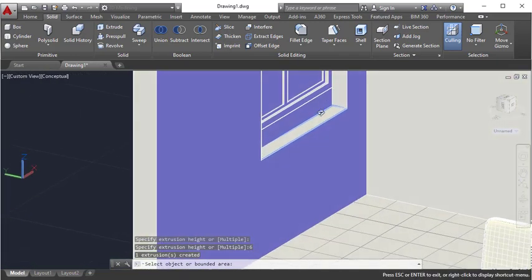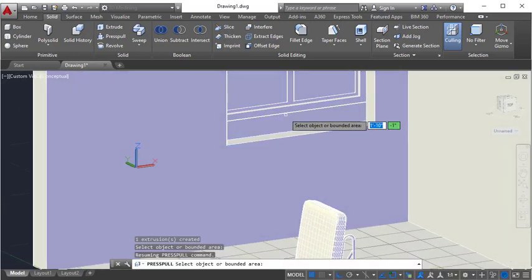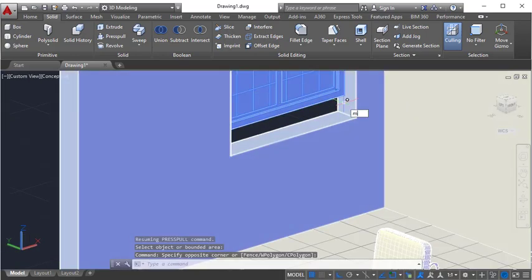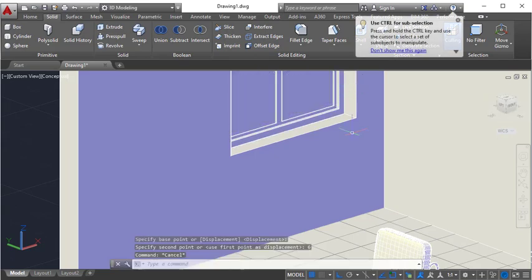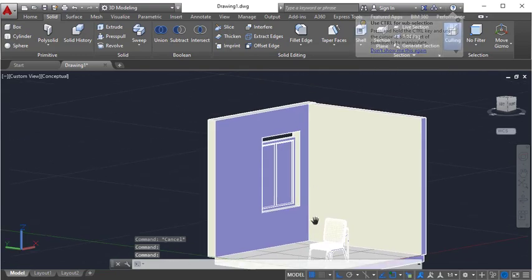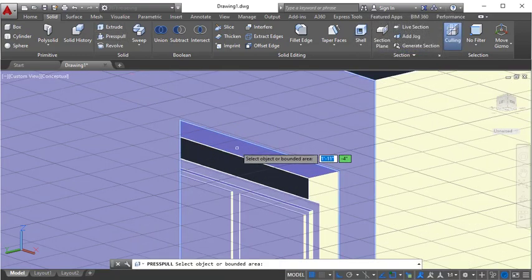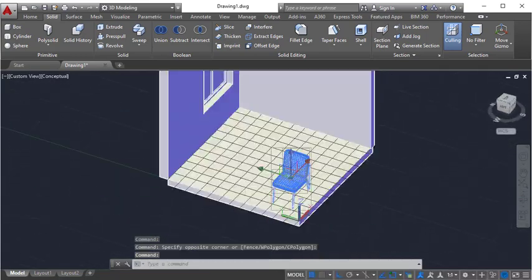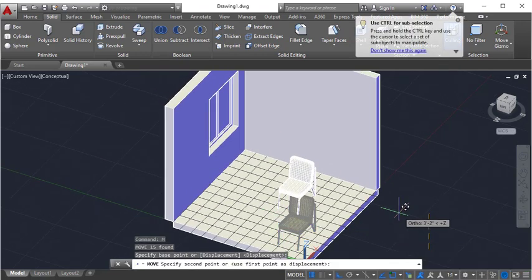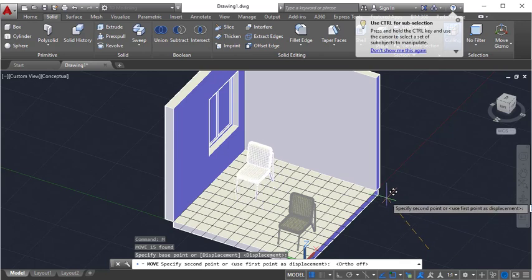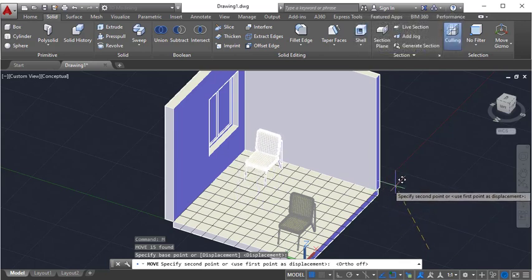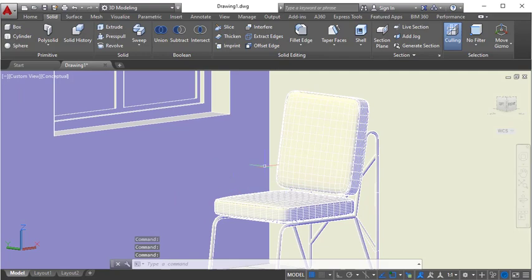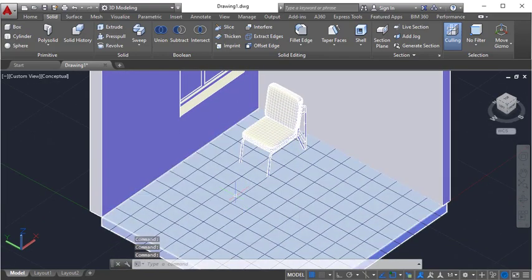Now snapping, like select all these options, enter in vertical direction 6 inches. Now it's snapped there, so 2.5 inches from the ground. Push pull 6 inches. Now it's covered, so I can select all these group, enter somewhere like F8, like this. I will place it near to the window, and like this is my viewing position, so I can make a rough table over here.